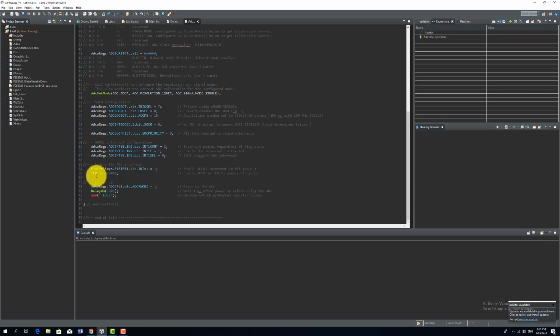In disabling an interrupt or a component or a part of your C program file, there are many ways. We can set this one equal to 0, meaning it's already disabled. But since in the procedure we have to comment out, we have to follow that procedure. How are we going to comment out? You only have to introduce two slashes, which represent a comment syntax on that specific line. That's why the color changes.